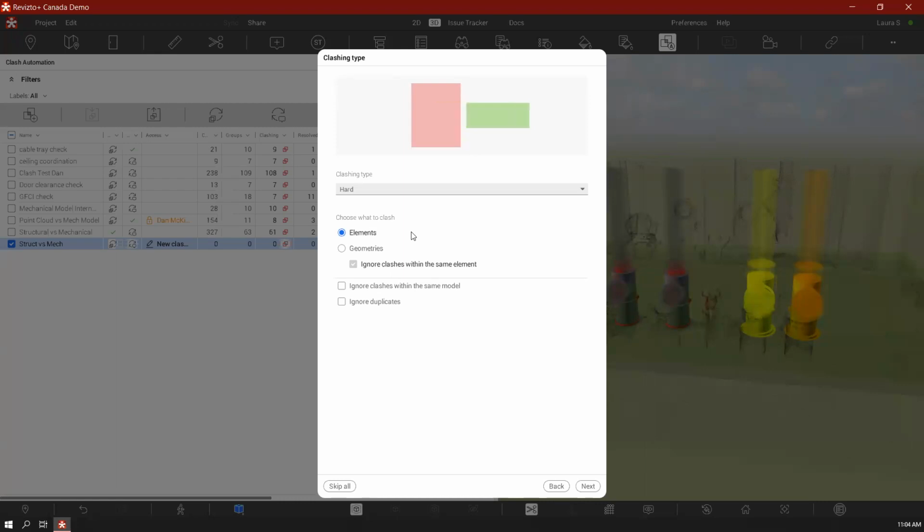So that is where we define what an element is. So those geometries that make up that door, we might want to clash that. We might want to come up with something specific that, you know, we're clashing only a clearance, or perhaps just the frame is important. So we could definitely create a search set that uses just the geometry to clash.